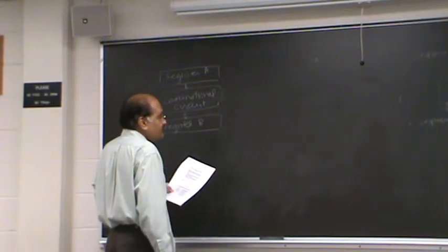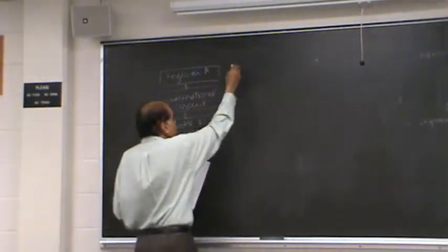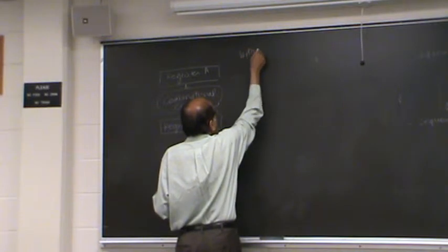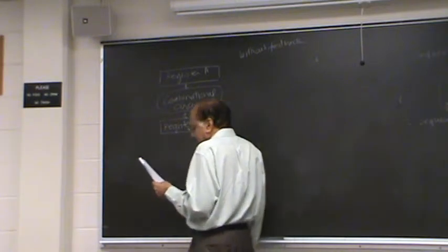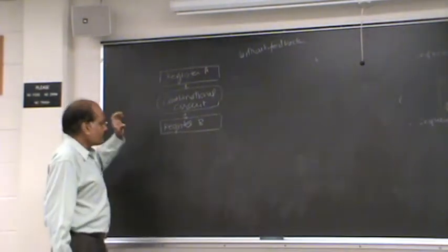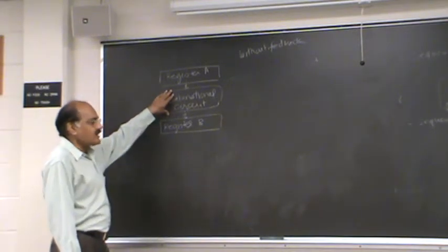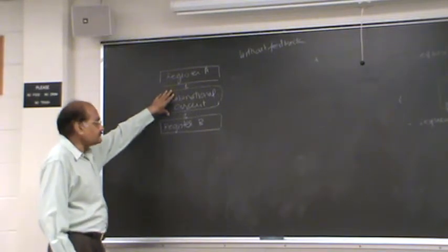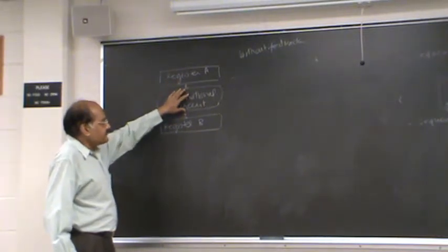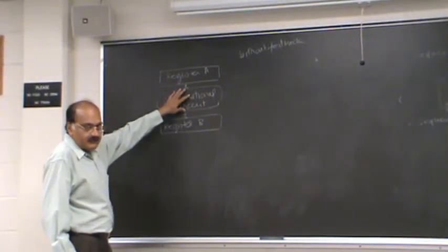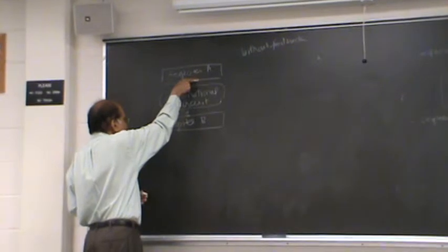so this is the problem we want to consider. That is the case, sequential circuit without feedback. So this is a without feedback case. Now here's the problem. You want to test this combinational circuit. All the faults are in the combinational circuit. That's our assumption. So, let us assume that we have generated a bunch of tests for testing the combinational circuit. Then, our challenge is, how do we apply the tests here?